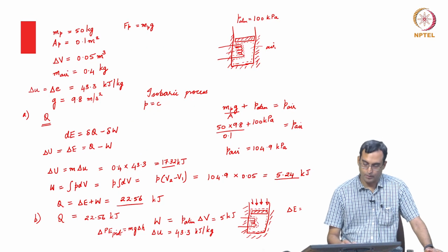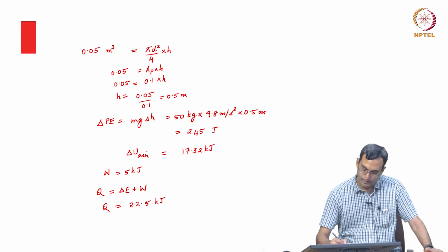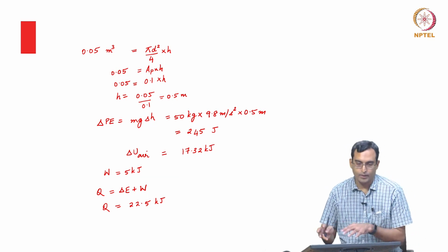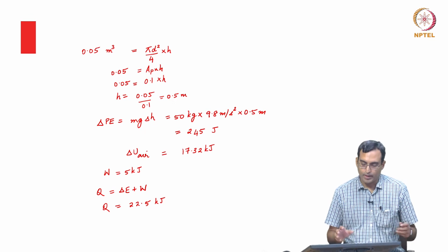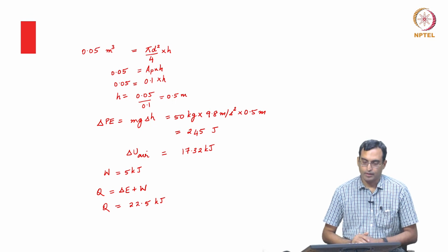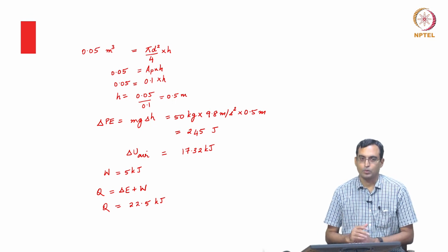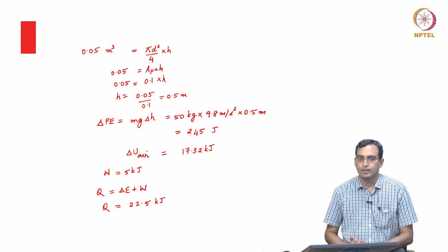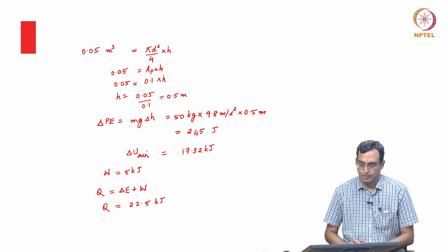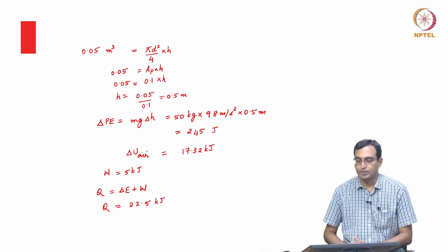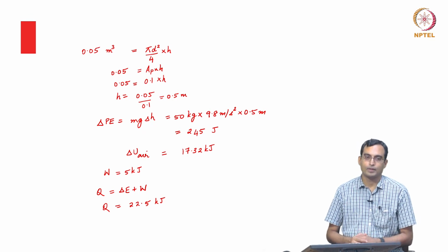We see earlier that we got 22.56. I did not add the second digits in this case, you would get the same. So, I can do this exercise in this fashion. I see that because of the way in which we define the system, the values of the work and the heat and internal energy in general can change. In this particular case, because I use a different system in the two cases, the work has changed and the energy change has changed, but the heat transfer is still the same. So, in this particular problem, the heat transfer does not change. So, I needn't have done this exercise, but it is reassuring to see that even if I do it, I get the same thing which I can deduce by logic initially without doing this problem.